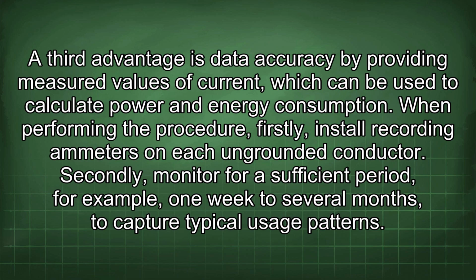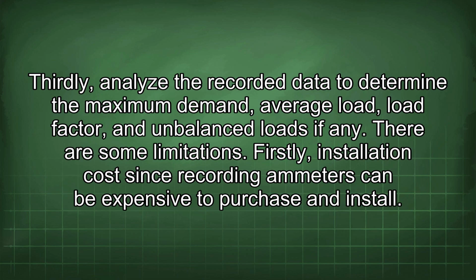Secondly, monitor for a sufficient period, for example, 1 week to several months, to capture typical usage patterns. Thirdly, analyze the recorded data to determine the maximum demand, average load, load factor, and unbalanced loads, if any. There are some limitations. Firstly, installation costs, since recording ammeters can be expensive to purchase and install.